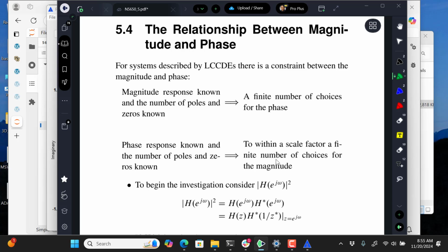And in the system I'm working on in my work, I had to come up with a filter for a transmitter that has to shape a spectrum so that it meets the NTIA spectral mask for SATCOM. So I wanted it to be linear phase, and I wanted the complexity to be minimized so that it could be implemented in FPGA.